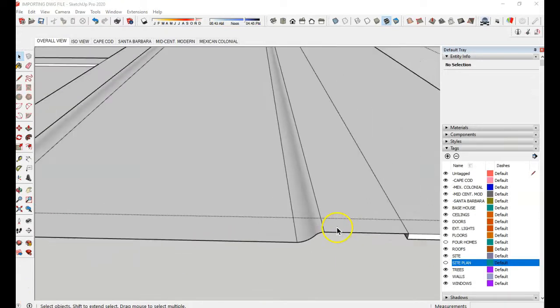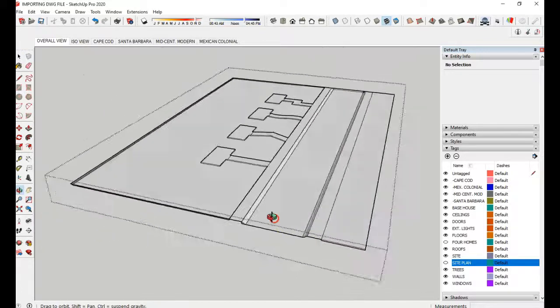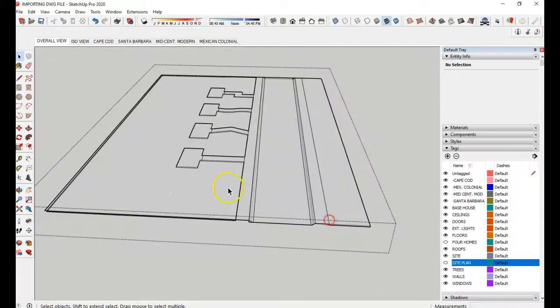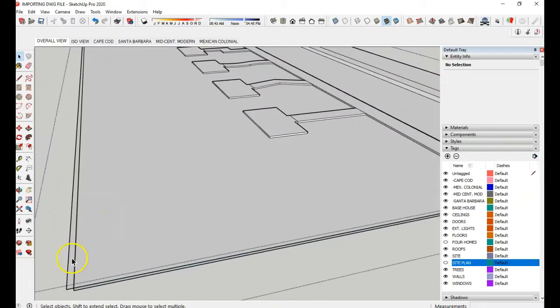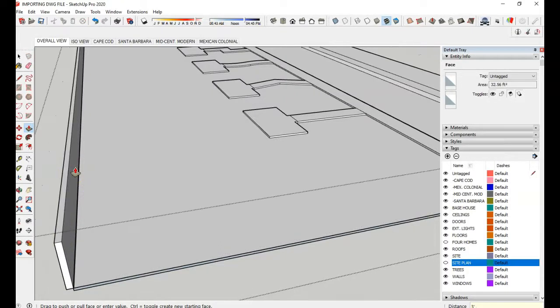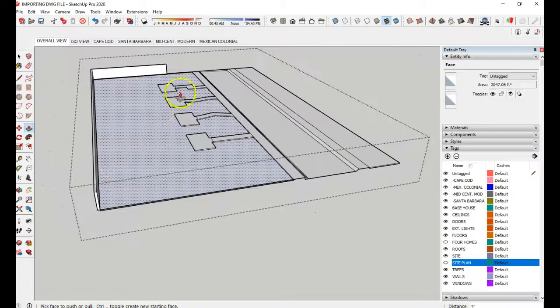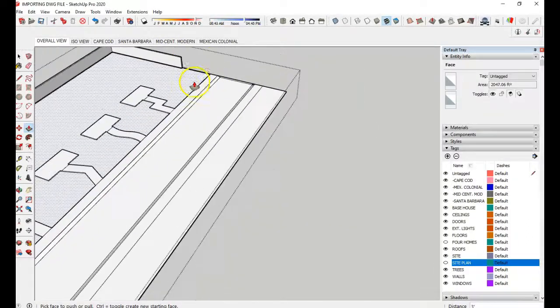After we make our curves on both sides, we can back out of our view. And the last thing to do is to raise this fence over here. So the top of the surface here, you can maybe raise it up 3 feet is fine, 36 inches for right now. You might have to modify this over here and add another little piece of wall here.